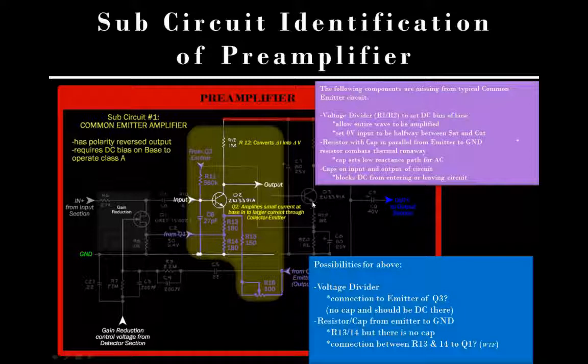Well, we know that there's going to be current flowing through that transistor if it's working. If there's current flowing through that transistor, then these two resistors are going to drop voltage. So they're a voltage divider. So there's going to be some voltage sitting there. Since this is connected to positive voltage, this is ground, that means this will be a positive voltage of some sort, getting back to this base. So that's a path that could be providing the DC for this transistor.